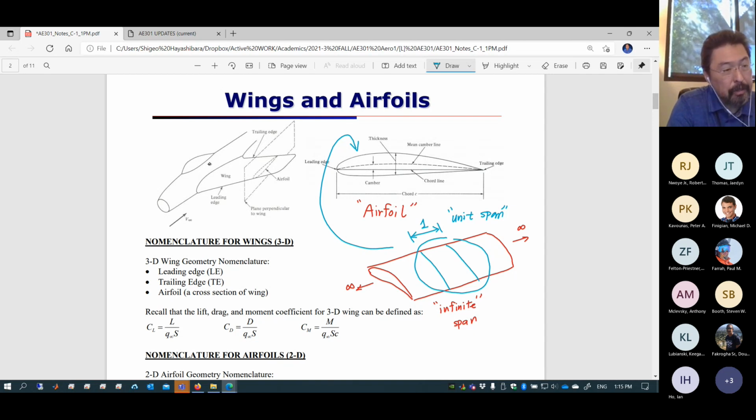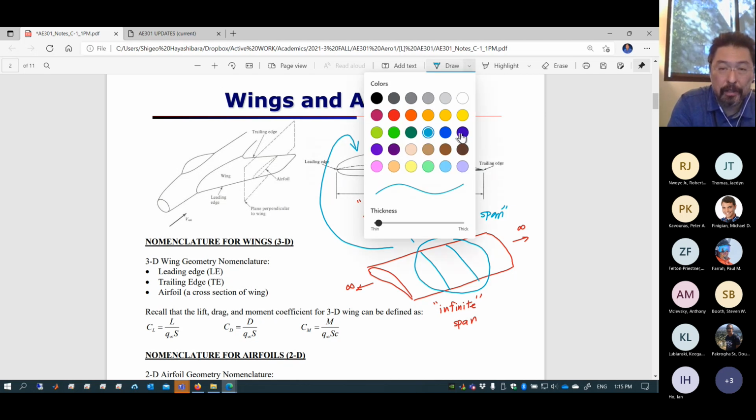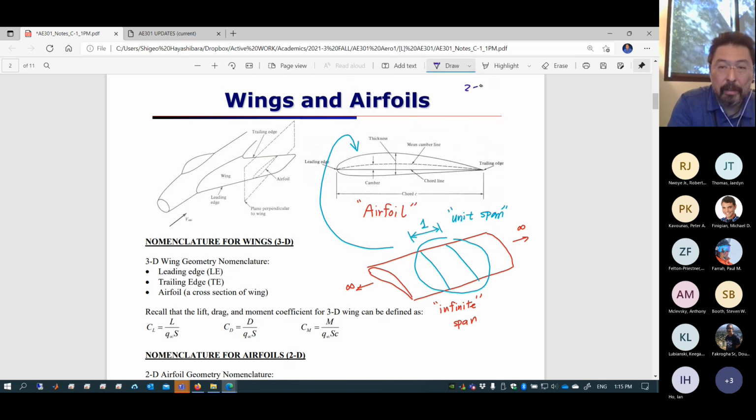But you can create your own wing introducing different shapes. I'm going to change the root and tip sections to different shapes, and then connect them up continuously and nicely. You can design such a thing if you're given 2 unique cross-sections as a database, the behavior of each airfoil. That is something you have to deal with. So for every design, you are going to start with 2D analysis. Suppose you choose to use 2 different kinds of airfoil, you're going to analyze both of them and understand the behavior. And then, and only then, use those databases to design a 3D wing. That's always the process.